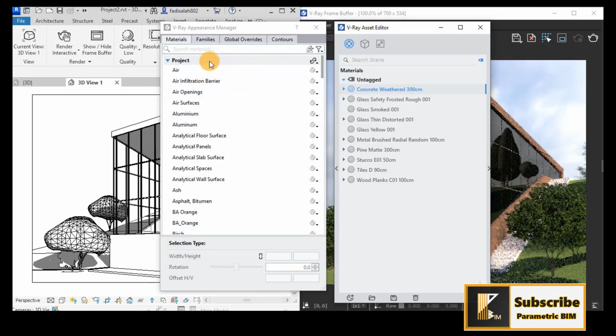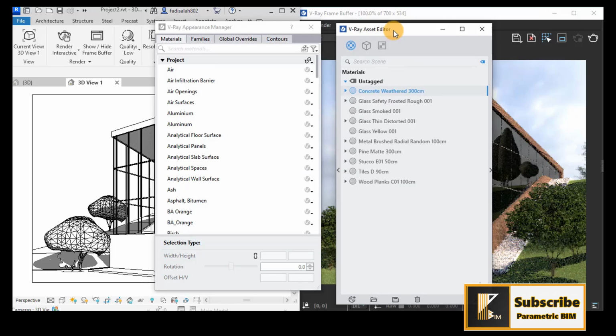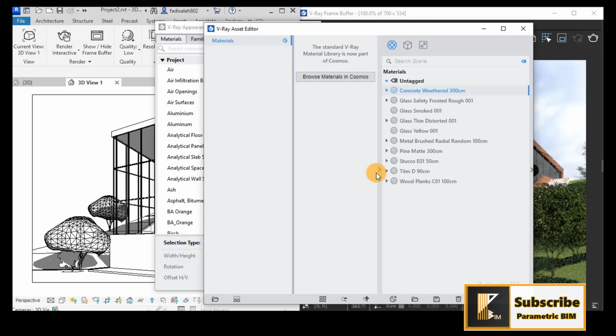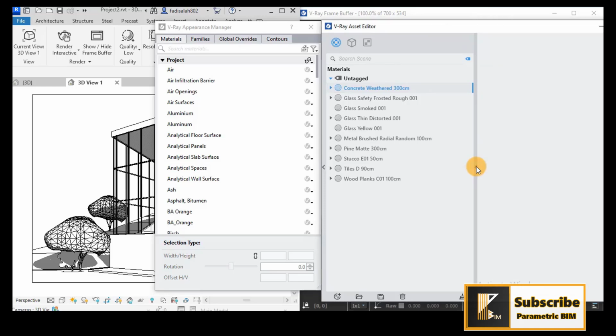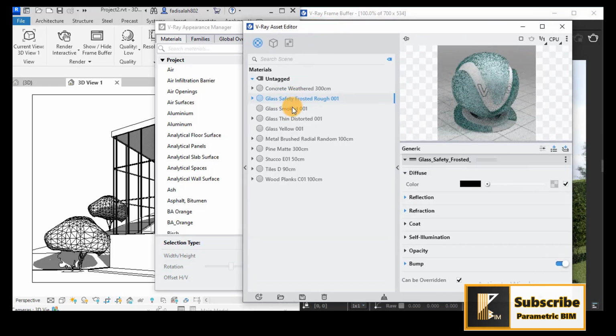Here you will have the Revit materials that you have in your project, and here you will have the Vray materials that you are downloading from the Cosmos library. If I click here on the side arrow, I will have a preview for each material with its properties such as reflection, refraction, the coat, the bump, and much more.